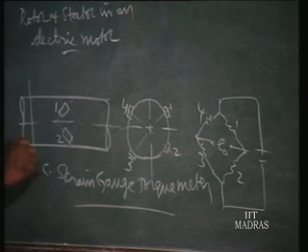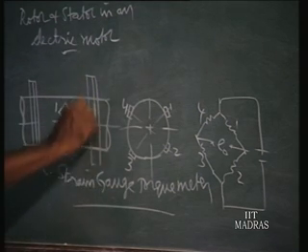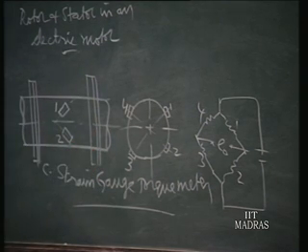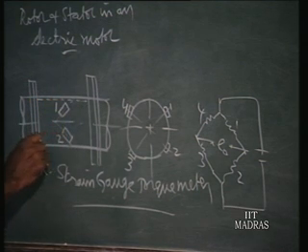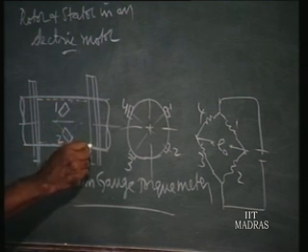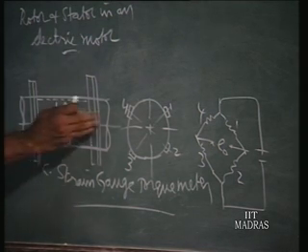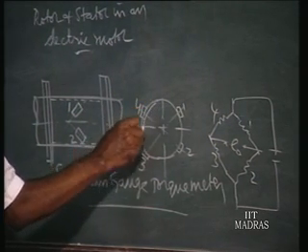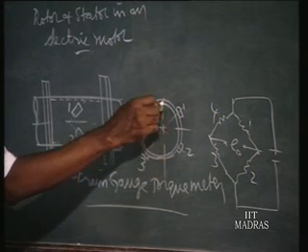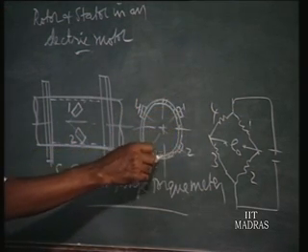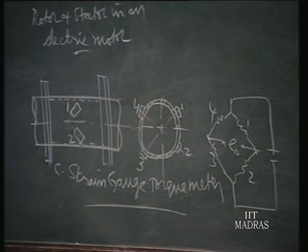So for that purpose you can make a flange joint, a flange coupling in between, and make a tubular member, that is where you want to fix the strain gauge. The other part may be solid. So here we are fixing the strain gauges on a tubular member, so that we have sufficient signal for the instrumentation. The signal to noise ratio will be sufficiently large.